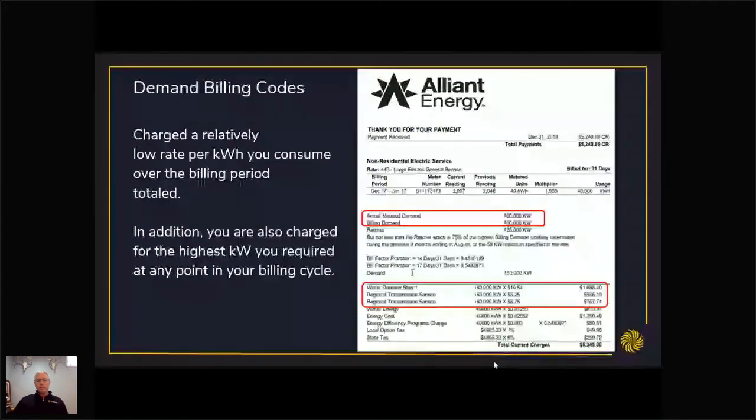So that doesn't necessarily correspond directly to total energy usage, because that could be a time where, say, 3 or 4 large machines started up all at the same time. So you have a very high draw at that period, but maybe that draw drops off. So the kilowatt usage can be a little difficult to put your finger on, just on an electric bill, as to when it is happening.